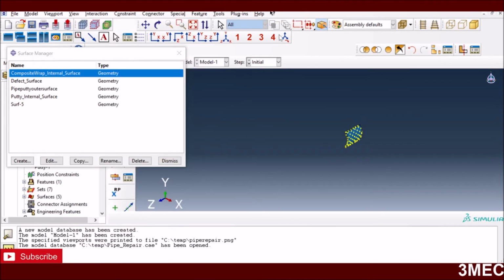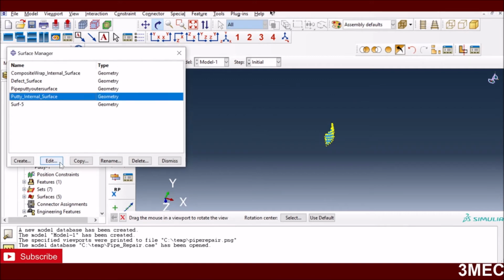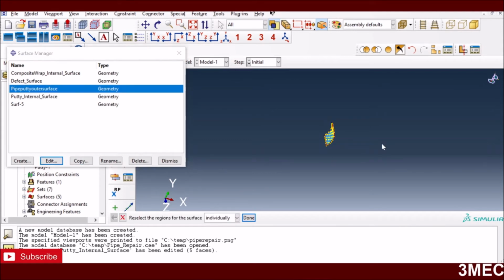Right, so now I have Putty here, and I can just rotate, and I need to create an internal surface and an external surface, because the external surface will be bonded with the wrap and the internal surface is bonded with the pipe. And that's how I have created the Putty inner surface. So you can see it highlights that. And then I have done the same with the Putty outer surface, which is the other side. Then I bring everything back.